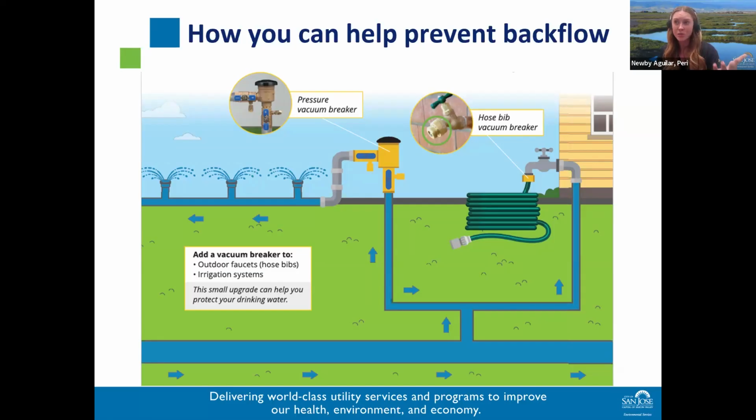However, I do think this is really important material for a property owner to understand, so that you can take a look at what your irrigation, your outdoor plumbing, or even internal plumbing looks like, to see where these backflow preventer devices might come up within your home. For a water retailer, our cross-connection control program is primarily based on a containment approach. So whereas these resources are great for isolation, our program actually runs on containment, which means that from a regulatory standpoint, we only focus on what happens at the water meter. So where your water enters your property, that's pretty much where we stop.